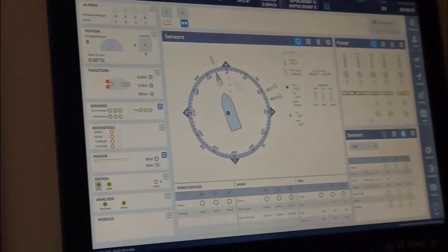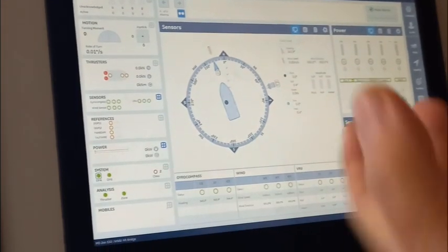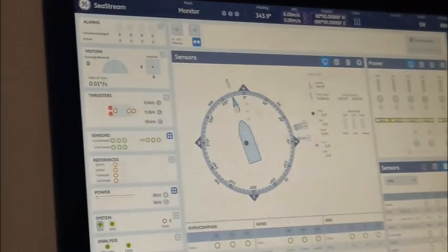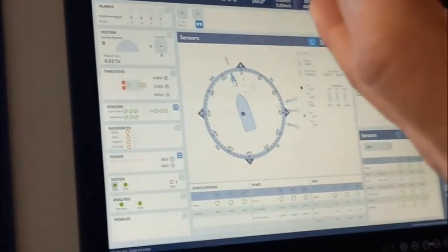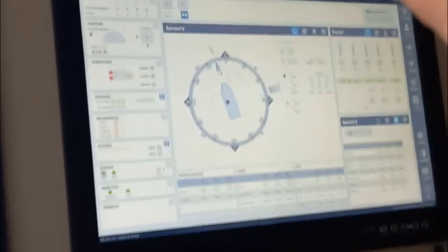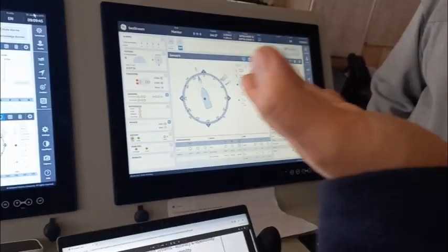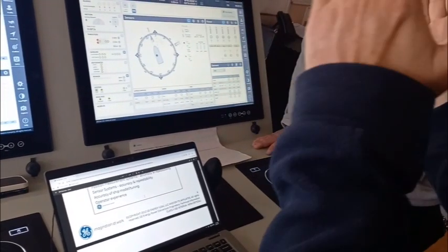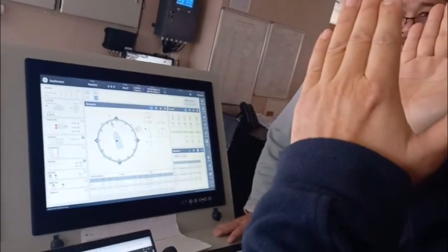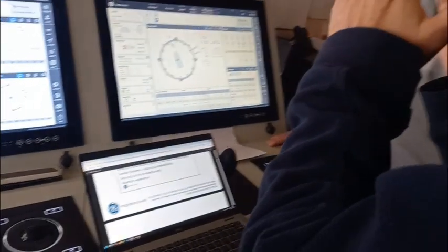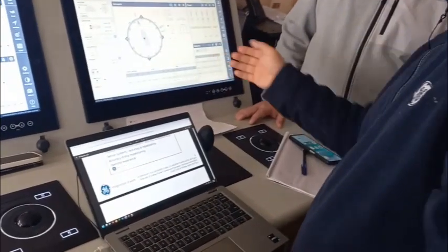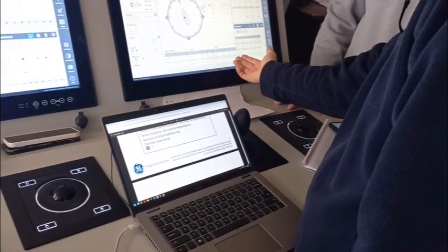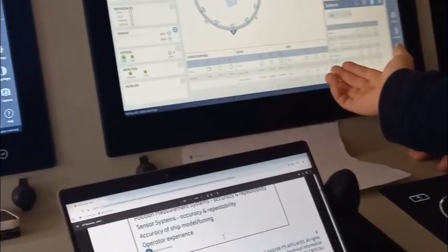When you install this VRU, because of the base, it's not always horizontal. So when you install it, the three VRUs may have different platforms, so they may have different output telegrams to DP with different data. But the vessel is at a fixed angle when docked at the shipyard. So we need to calibrate it after the installation to make sure the output telegram of each matches the others: 0, 0, 0, each roll 0.4, 0.4, 0.4.